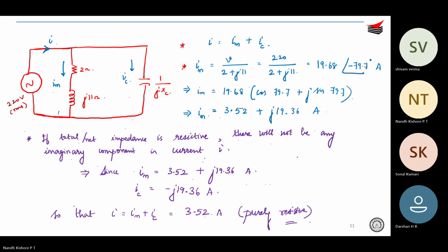Yes, sir. Okay, so now what is this negative part signifying? We will calculate the capacitor and all, that's fine, but what is the negative part signifying? Generally, with the convention that we have considered, IC is entering over here. Current entering the capacitor is considered positive, and current entering the motor is considered positive.